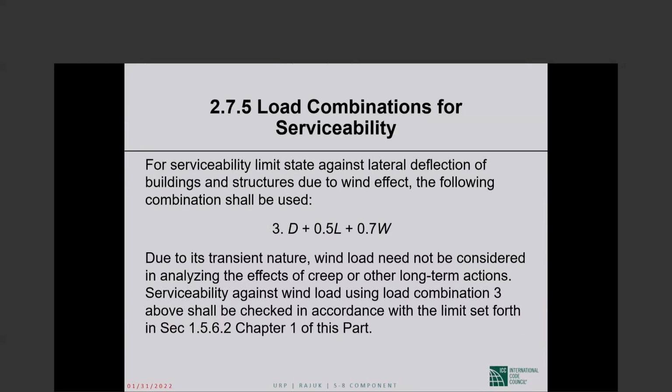Okay. We are concerned about strength in seismic design, not serviceability. It is understood that there will be damage and things. For the serviceability limit state against lateral deflection of buildings and structures due to wind effect, the following combination shall be used. Okay. Dead plus 0.5 live plus 0.7 wind.